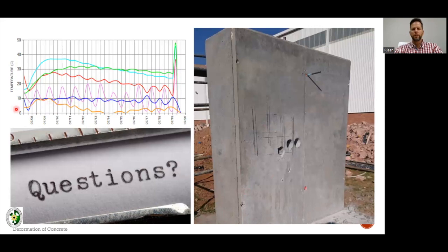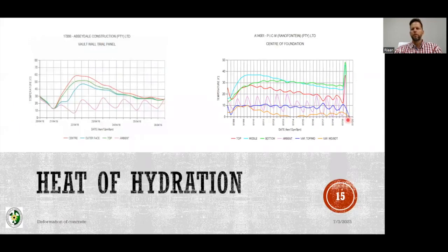Okay, so the question here is, what causes the spike in temperatures on the 20th of July? Looking at this little graph over here, there's a spike in temperature. The temperature probes were then disconnected. Have a look at the lines, it's the green one under the ground. There was probably a disconnection or something that happened with these temperature probes, because these probes are connected to a piece of wire that then runs to wherever it goes.